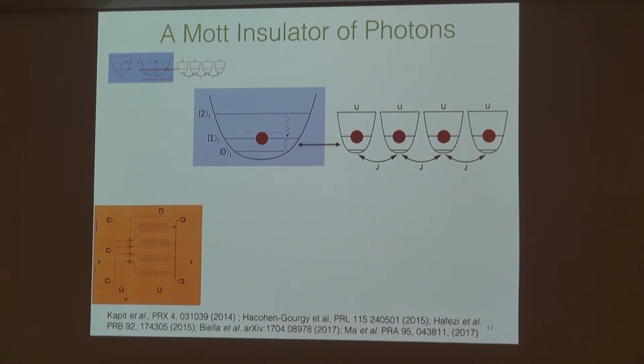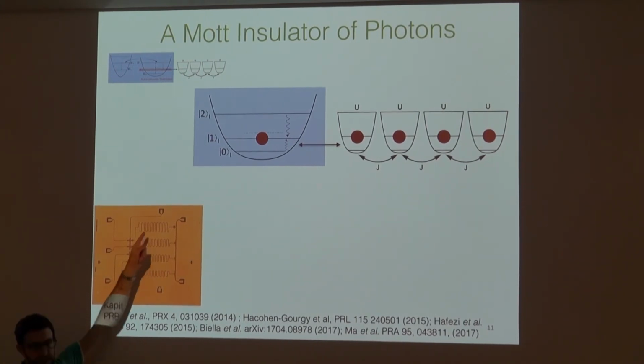So we're not going to talk about how transmon qubits work internally. They're basically LC oscillators, where the L is a nonlinear inductor coming from the Josephson tunneling through some very narrow oxide layer. But just think of it as a nonlinear LC oscillator, but nonlinear at the single photon level. So there's capacitive coupling between the qubits. These bias lines allow us to tune the frequency of the individual qubits to make the lattice sites all the same energy. And these are readout resonators that allow us to measure with high fidelity the occupation of a single lattice site. So you can think of this as a kind of microwave quantum gas microscope, but a little quantum gas microscope.